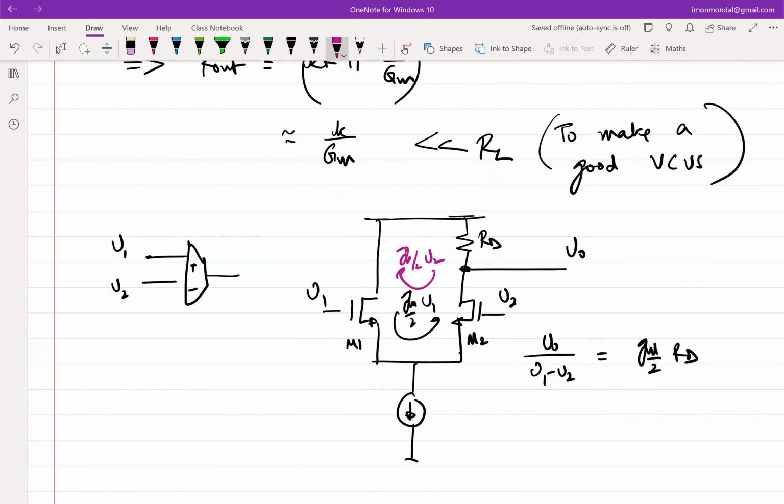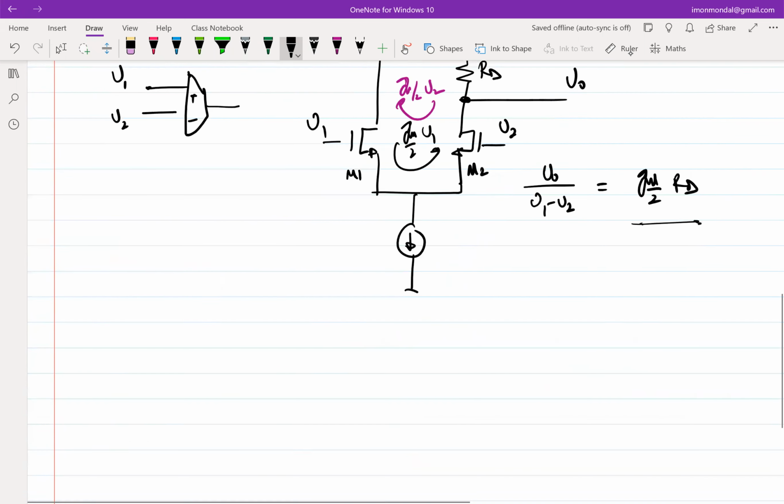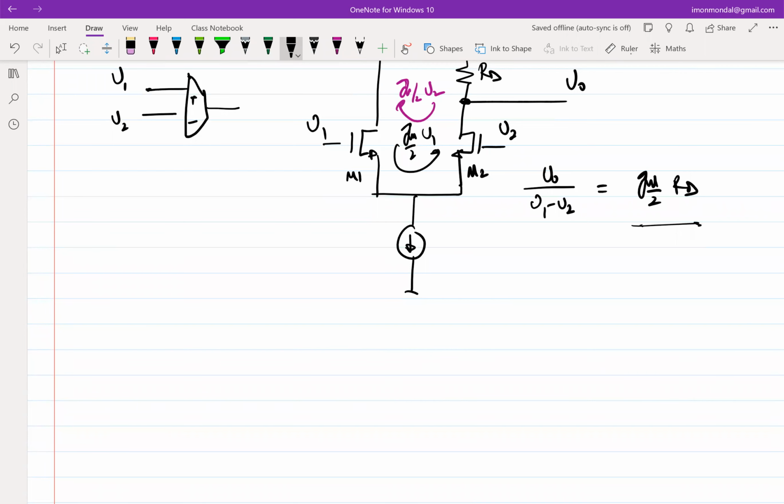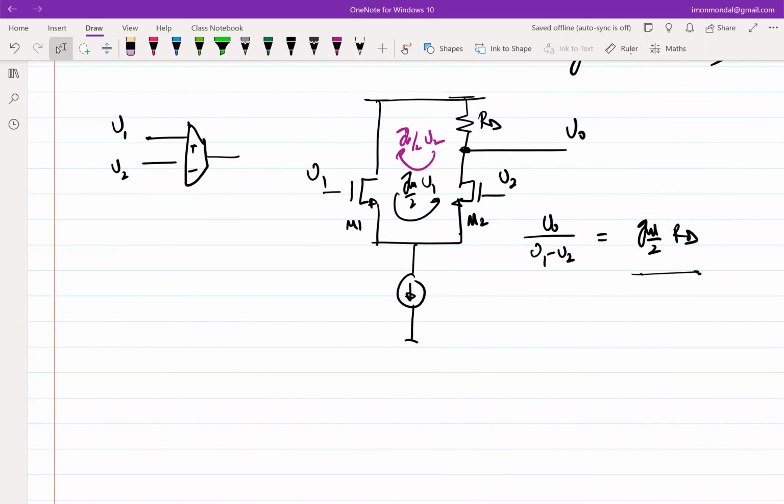Okay. So now this expression is basically the expression of a common source amplifier obtained from a different circuit. So all the problems of the common source amplifier naturally translate to a diff pair. Now, in the last couple of classes, we figured out how to improve the gain of a common source amplifier without increasing the power supply. And that is the same thing we can do in this case also, right? So help me out. What should we do? What is the only major change that we need to do? Yeah, replace RD with a PMOS.